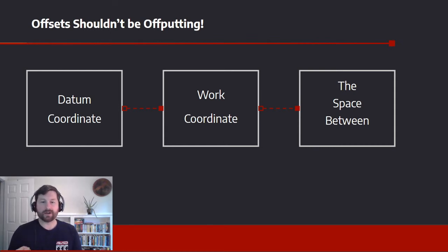Or we can stack offsets. And so we can stack offsets in CAD, we can stack offsets in CAM, and we can do offsets in the machine controller itself in Mach 4. And so we're going to talk about those.